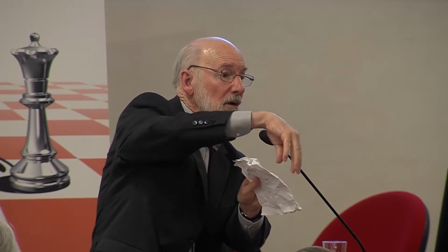And interestingly, the outsides are perfectly wetted, remember? And on the outside, many different phases will nucleate. So when we're cooling steels from the austenite range, when it changes over to ferrite, the ferrite always nucleates here. So I'm jumping ahead of myself.